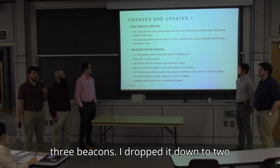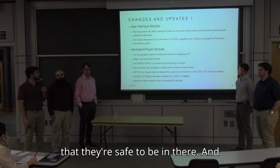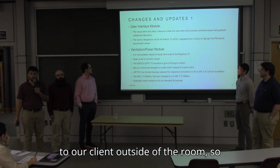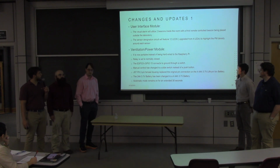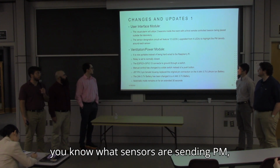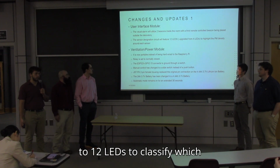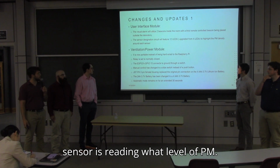It was originally 3 beacons. I dropped it down to 2 because there's no point telling them that they're safe to be in there. And then we added a 3rd beacon per request of our client outside of the room, so users outside know before walking in what the levels are in there. And then the sensor designation has been updated. Originally it was just 4 LEDs to let you know which sensors are sending PM, particulate matter. But I've updated that to 12 LEDs to classify which sensor is reading what level of PM.